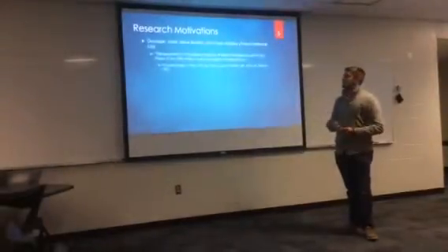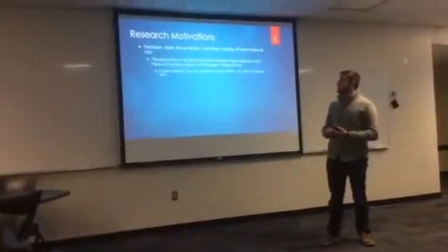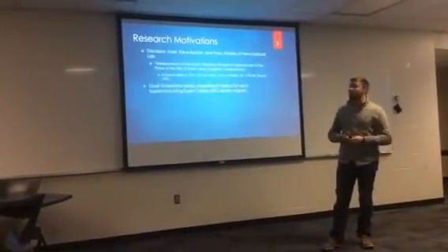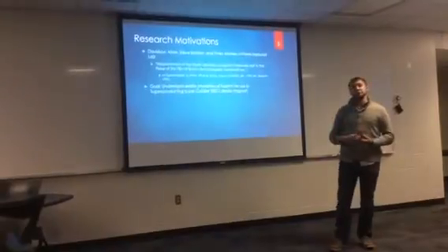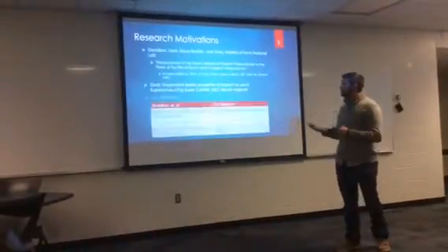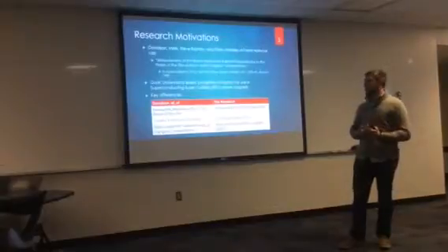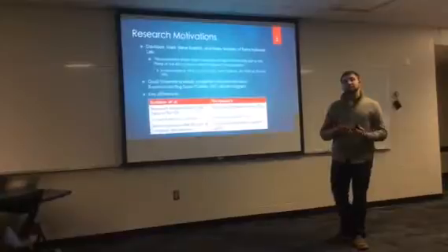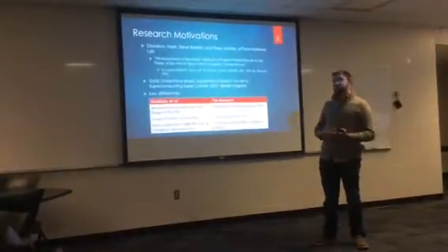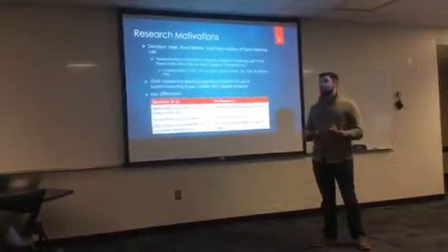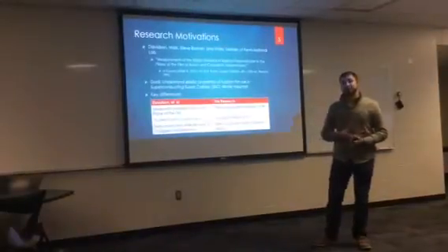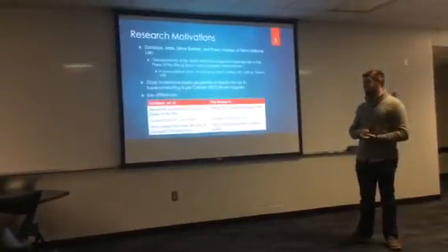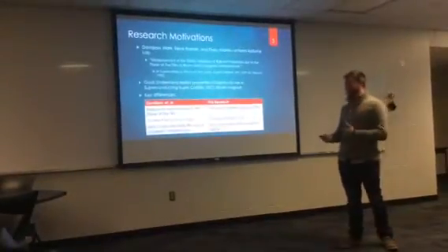So the motivation behind this study is work done by Mark Davidson and his team from Fermi National Lab. They measured the elastic properties of Kapton for use in superconducting supercollider magnets. But there are a few key differences in Davidson's study versus my own. Davidson and his team measured perpendicular to the plane of the film, whereas my study measured parallel to the plane of the film. Davidson's team studied Kapton, which is a polyimide, while I studied ULTRALAM, which is an LCP. And finally, Davidson and his team's tests were conducted at a cryogenic temperature, while mine were conducted after cryogenic aging.